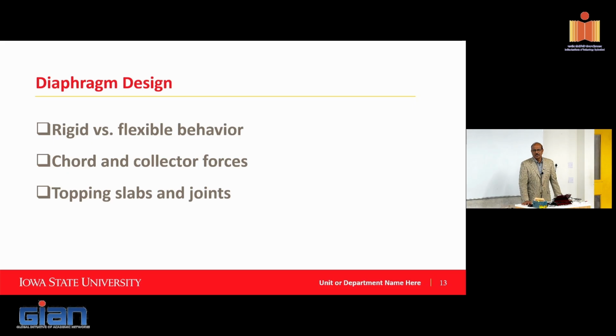Often precast diaphragms get questioned in terms of how they would accommodate some of the displacements that columns and beams go through. But if you look at the cast in place world, the demands are the same. But when they go through the approval process, if it's precast, they flag it, not necessarily cast in place.